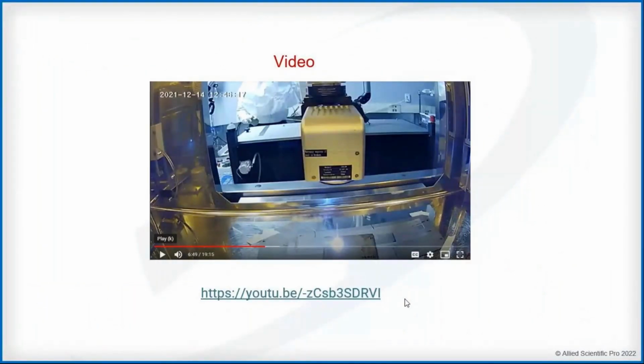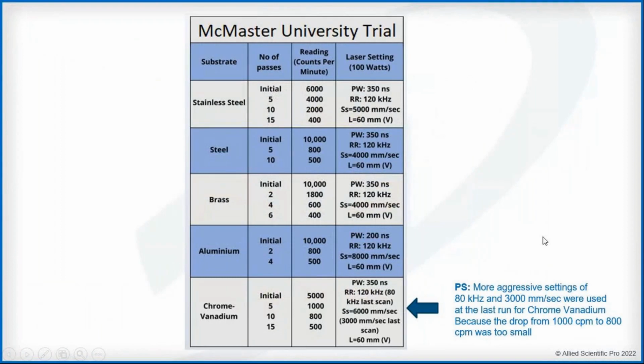So these are the results that we got. So you can see for stainless steel, chrome vanadium, we use 350 nanosecond, and for aluminum, we use 200. For brass, we should have used 200, but for whatever reason, we used 350. If we were going back there, we would have used 200 nanosecond for brass as well, because it's also a soft metal. So you can see there's less number of passes required for aluminum and brass as compared to the hard metals because it's more difficult to remove the contamination from them.